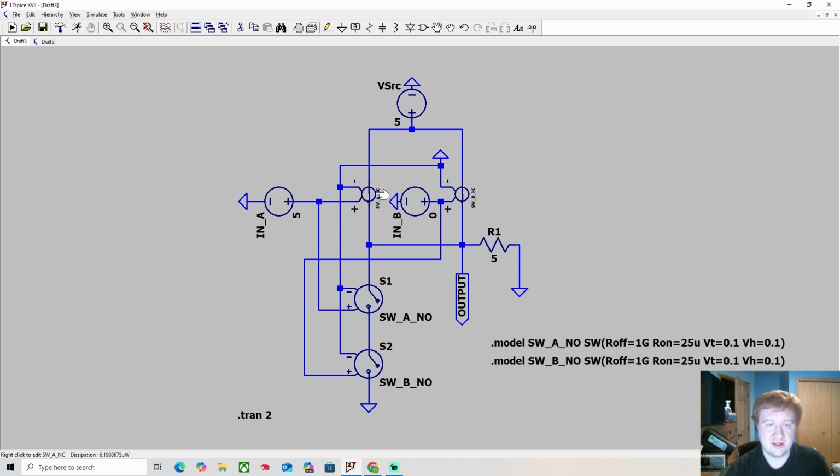So it would open this switch, meaning that there's no continuity between this top 5 voltage and this branch here. So you wouldn't have current coming through this switch. You would have 5 volts here and 0 volts if there was nothing else on the other side. Like imagine that this was not connected here, you would have 0 volts.